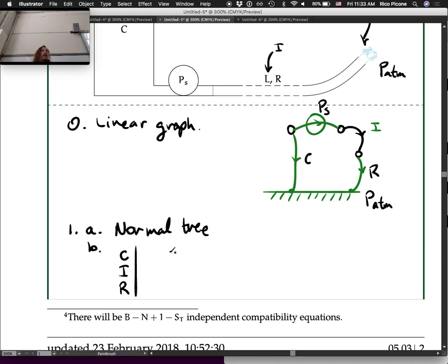So they're all going to be the cross variable equals through variable times the impedance, right? The across variable in a fluid system is pressure. So PC, and these are all in the Laplace domain, and I'm not going to write (s) 50 times. I'm instead just going to suppress that, but we know these are all in the Laplace domain. So PC equals, the through variable is Q, right? QC, the flow rate, times the impedance, ZC.